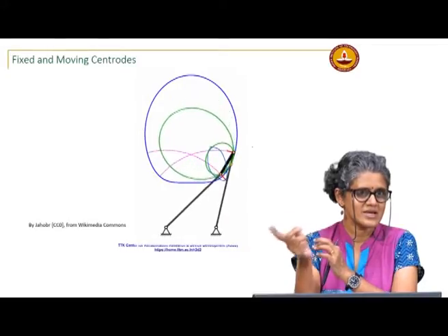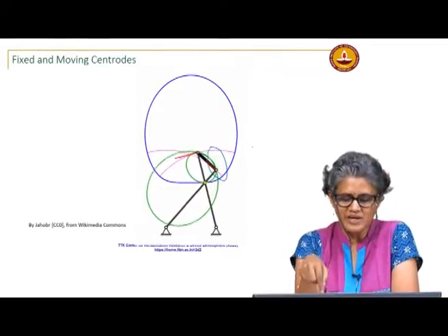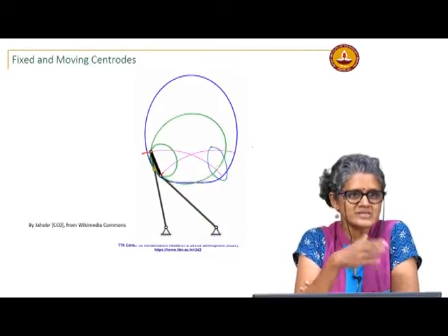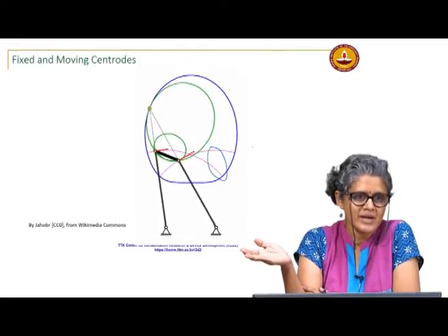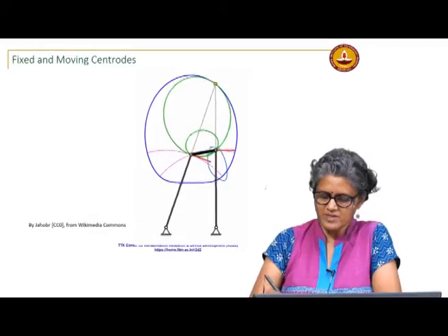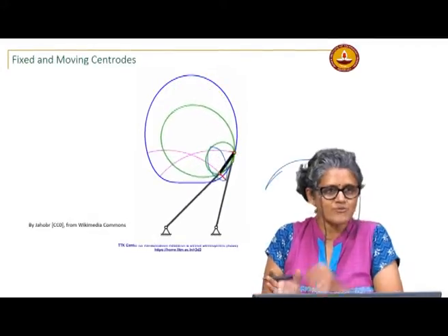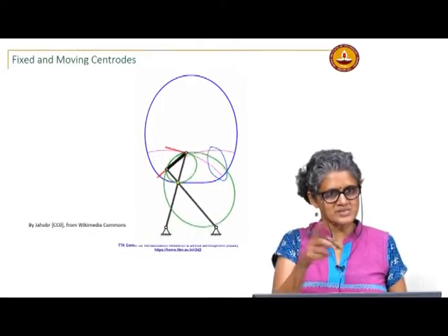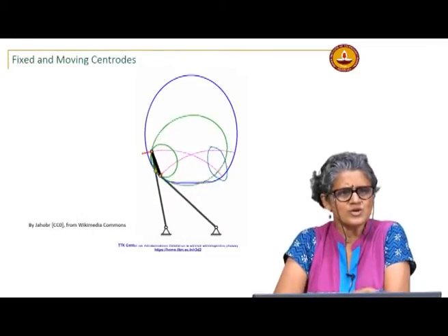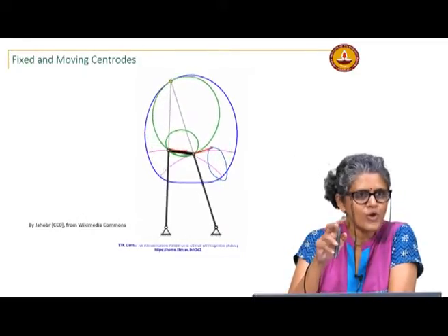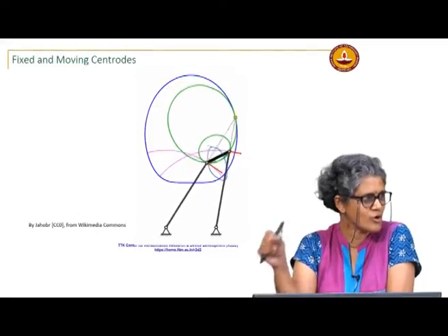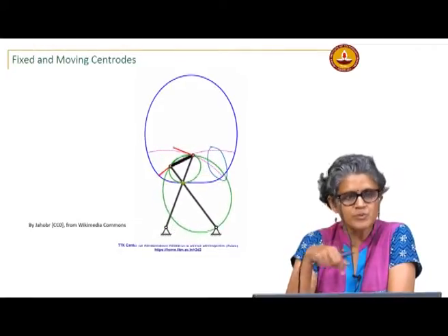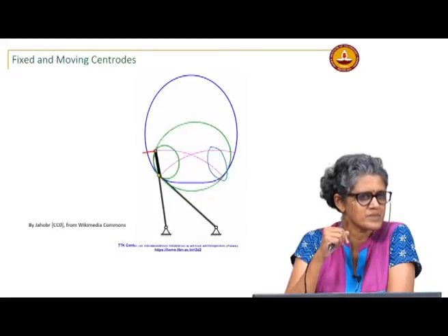Then all the rockers will have to. All the rockers will have, but we do not really consider that, because it's the degenerate case, you only get a circular arc. So, the circular arc is basically like something with a double cusp, kind of collapsed. That's essentially what the circular arc is. So, a true coupler point, something that is not on the input or the output link, on the crank or the follower, will probably have only one cusp, okay.